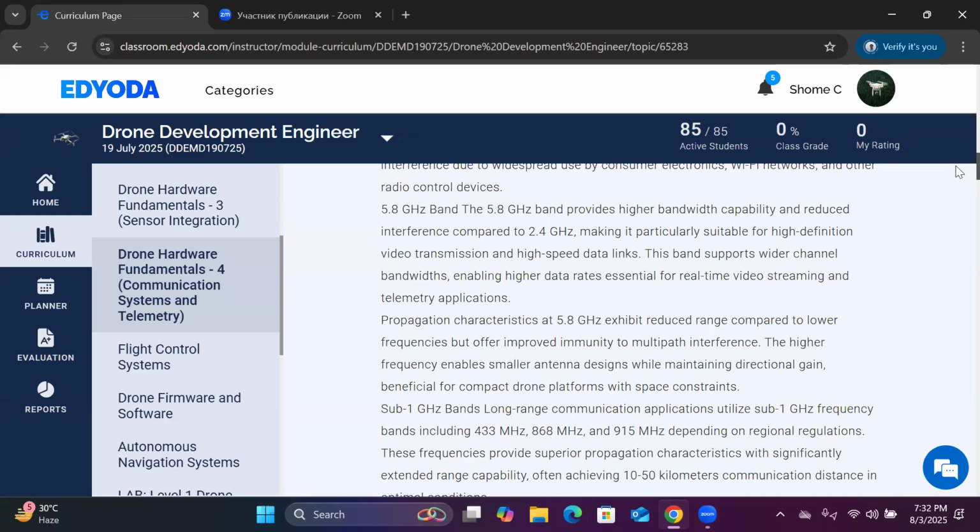So in that case, if we take an antenna, say there is a manufacturer for antenna, most of the companies use that is called Taoglas. So if you use some antennas from Taoglas, which are omnidirectional antennas supporting 2.4 gigahertz and 5.8 gigahertz, they will be the dual band antenna.